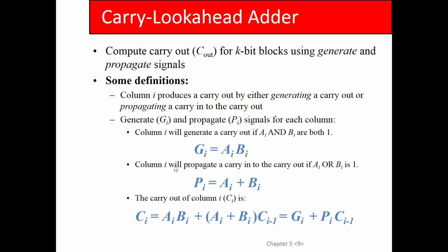And if you tell the synthesizer just to do an add, like I did over here with this counter, where I just put an add in there, well, the synthesizer has to know how to implement that add, and so it's going to rely on predefined ways to do adder architectures. You guys with me? So building an adder is not something that can be done systematically. Some designer had to figure out how to do an adder, is my point. Okay, so one way to do it is the carry-lookahead adder.